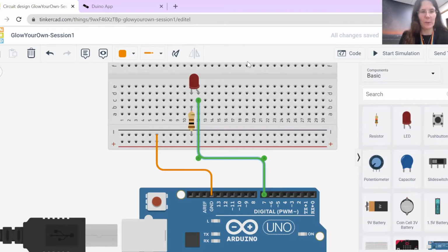Like I said, this is very low power, we're all fine with this, but the kind of circuits that some of the others work with, Tristan works with, you could hurt yourself if you pulled out a resistor while that circuit has power. And we don't want Tristan to hurt himself. So we're going to make sure that we always disconnect our power.